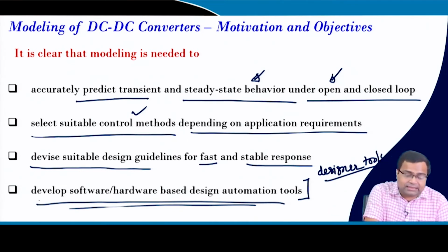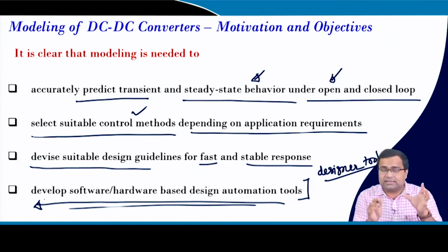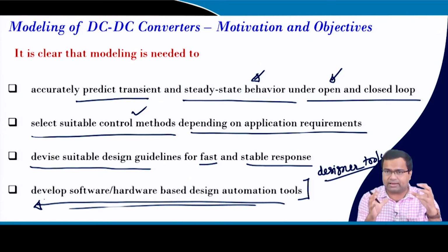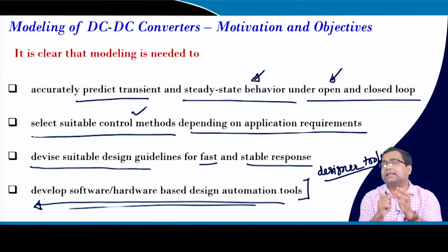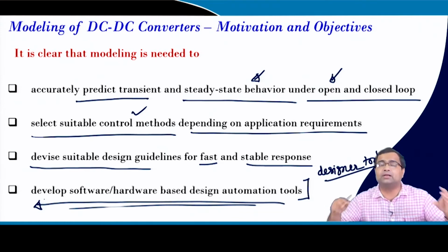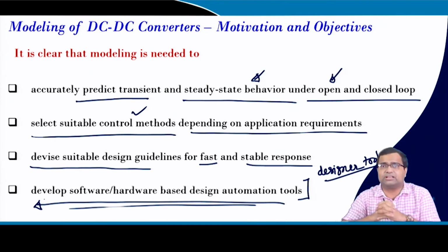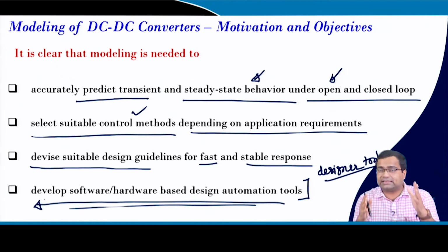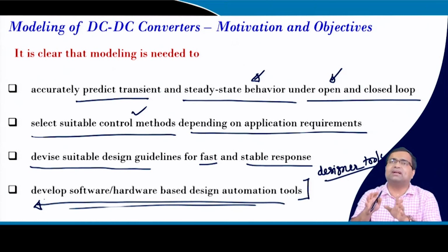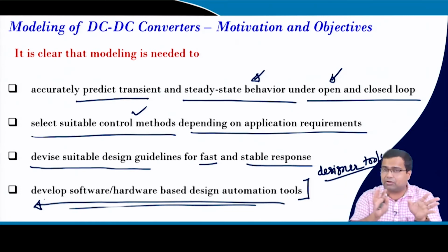In fact, in this course whenever we go for design, I will demonstrate some MATLAB .m file where, if you specify some gain margin and phase margin, or even some phase margin and control bandwidth, it will give us the compensator gain for a given inductor, capacitor, input voltage and output voltage. Then you can obtain the compensator, plug it in, and match the response of the model as well as the switch simulation.